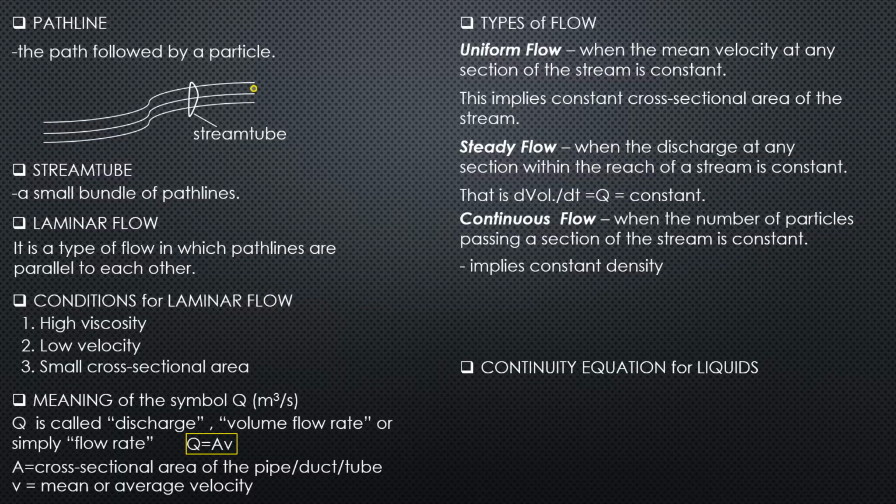So liquids are in general incompressible when the pressure that will develop normally is in kilopascals. It seldom reaches megapascals unless for LPG gases. But in most engineering flow, the pressure will only be in kilopascals level. So that's why the liquids are considered incompressible.